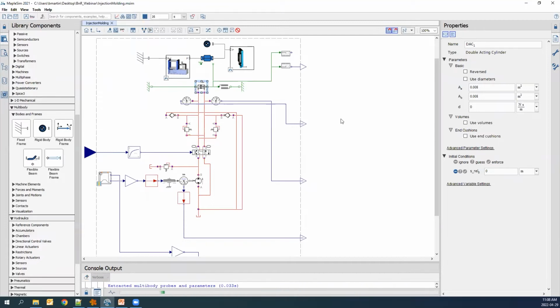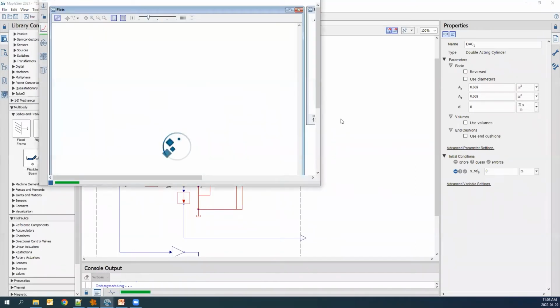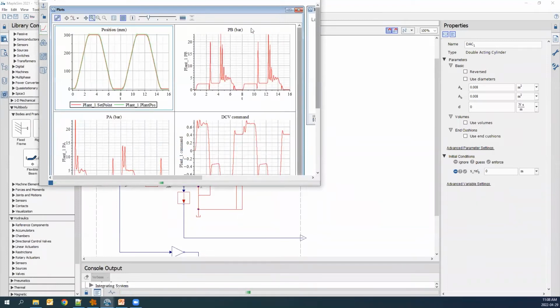Again, to get the 3D visualization here, I've used the CAD toolbox. So I've imported a CAD file, and that allows me to bring in all the mass and inertia properties and really gives me a much more accurate simulation. Because this is equation-based and physics-driven, you really want to make sure those masses and inertias are correct, otherwise your results will be off.